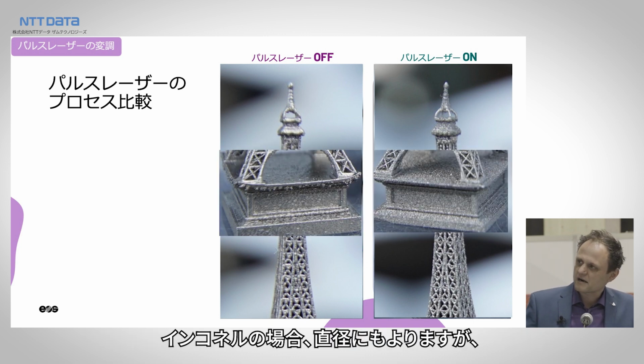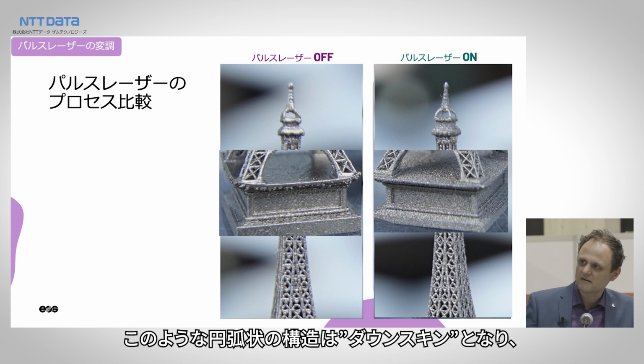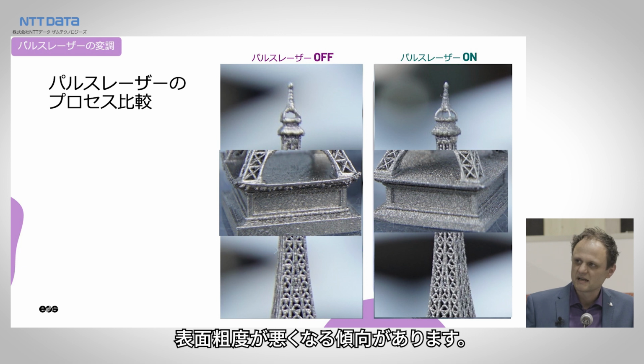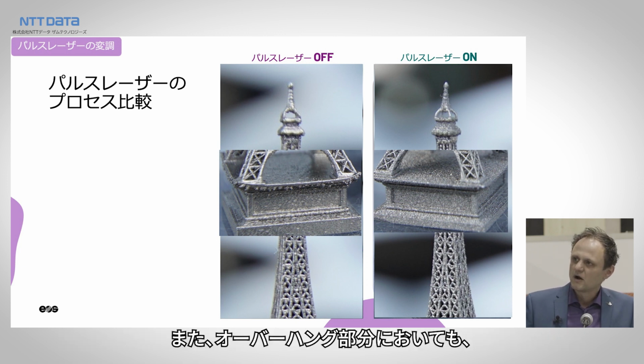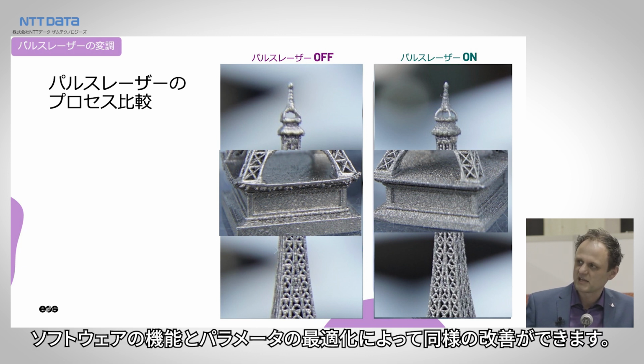Or these arc structures, so they tend to have, like in Inconel, depending on the diameter, these bad downskin surfaces. This can all be corrected. Or even in overhang regions, this kind of curling effect can all be healed quite substantially by just a software feature and a parameter optimization.